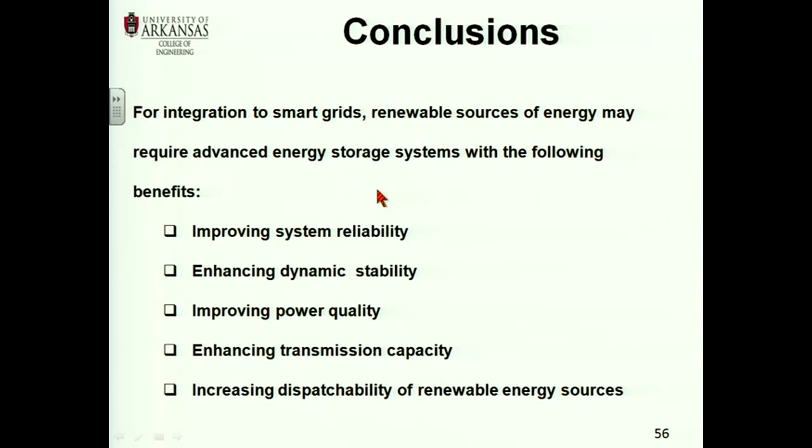Well, what about energy storage? Right, a battery can be used as a spinning reserve. In the Northeast, New York, New Hampshire, all those places, they're starting to accept that energy storage can be a participant. And we have run some simulations using historical data, and most of the time the spinning reserve is not being called to participate.